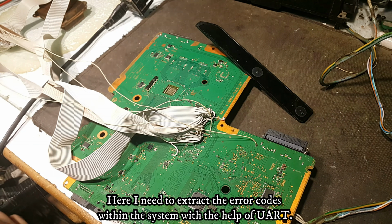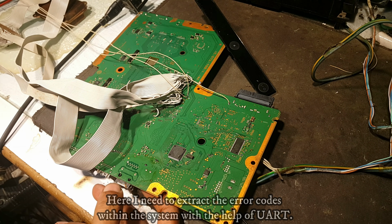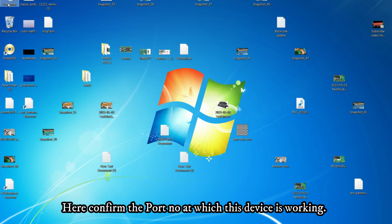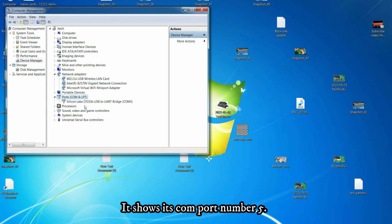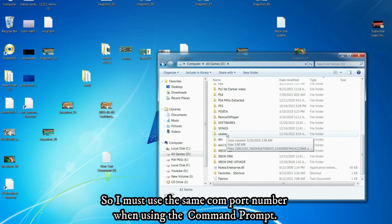Here I need to extract the error codes within the system with the help of UART. For this I have connected the UART to the computer. Here I confirm the port at which this device is working. There is a COM port to be used. I can see its port number there. It shows COM port number 5. So I must use the same COM port number when using the command prompt.